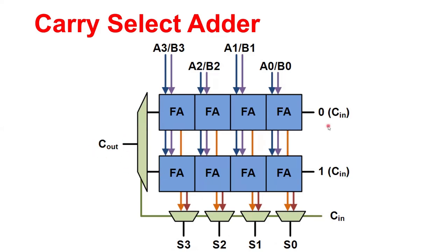So the conclusion here can be drawn in favor of a carry select adder, that although it consumes more power due to extra hardware, it is efficient in reducing delay as compared to the standalone carry ripple adder.